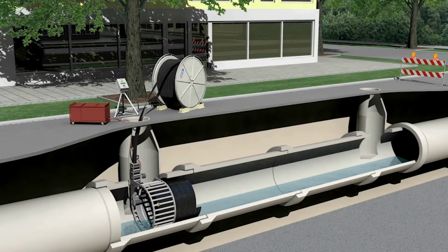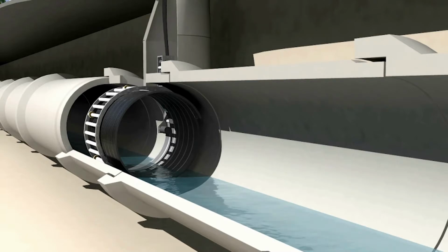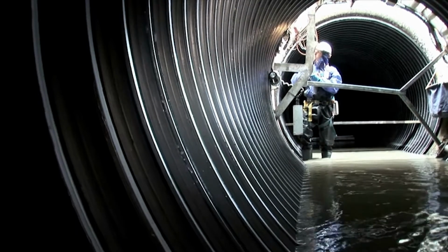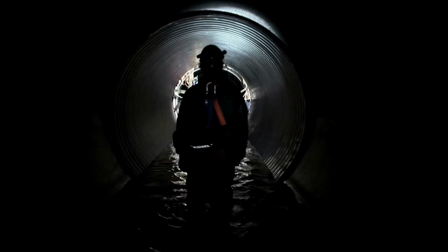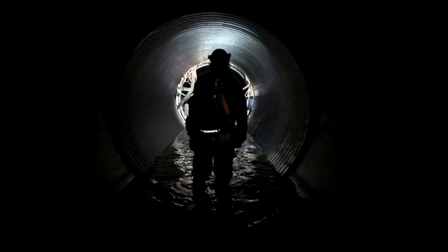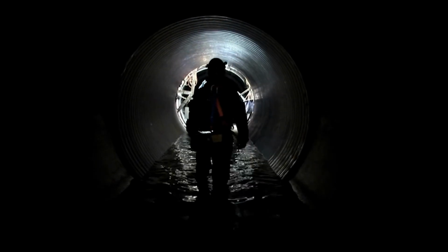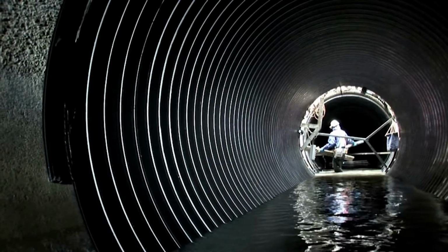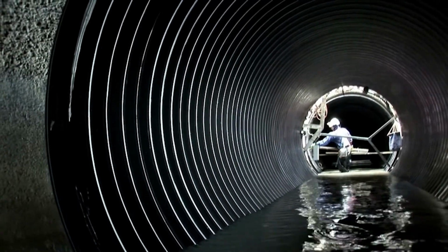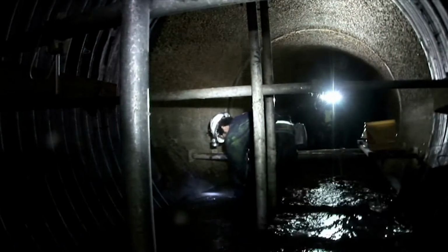The profile is fed into the machine from a spool above ground. The winding machine joins the profile strips together and progressively forms a new pipe within the pipe. The diameter of the pipe is slightly smaller than the host pipe's diameter to allow it to fit through the existing pipeline. To overcome friction while winding, the sewer flow is controlled to float the liner and allow long rehabilitation